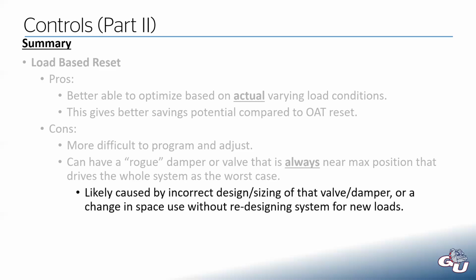And this is likely caused by bad design or bad sizing of that valve or that damper, or maybe they changed how that space was used without redesigning the system. One example might be, let's say you have a chilled water system and there's a space that used to be an office, but they have decided to change it and load it up with a bunch of server equipment.